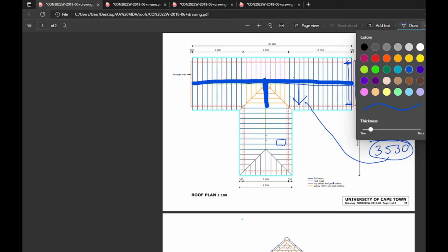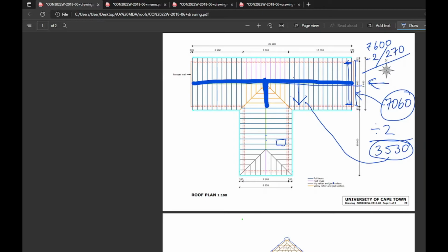So since we've come to the inside face, what else can we steal from the drawing to give us more information on what's going on here? Well, this again is not so obvious. 10,900 will take you to the edge of the roofing, but it doesn't take you to the inside face of this brick. So you have to make some assumptions again. 525 is our eaves distance on flat. We are going to assume there's also 525 that way, right? Okay, here's 525 as well.